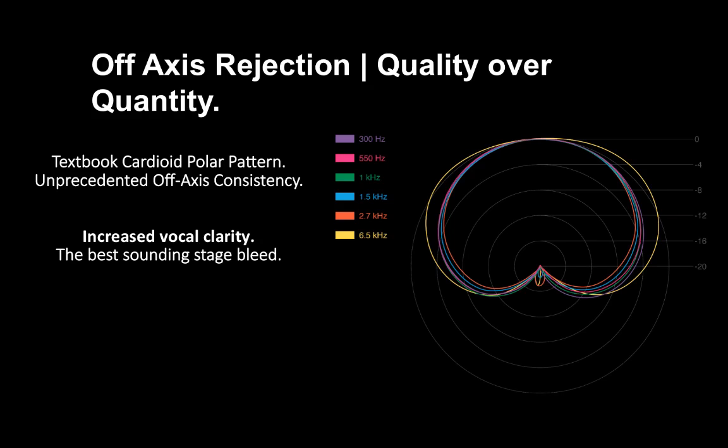And that's another thing again when you're talking about comparing microphones, right? Anybody when they just say they have a cardioid pattern microphone will show you just that basic sort of upside down heart shape. Say, look, it's cardioid, but you have to be able to look at it like you see it here at different frequencies and see, does it hold that cardioid pattern or hypercardioid or supercardioid, whatever it happens to be. At how many different frequencies does it still maintain that pattern? Because if it's really erratic at some frequencies and not at others, that's, again, what leads to that sort of colored off-axis response. But if it's consistent like this, that's the sign of a consistent pattern across frequencies, not just at one frequency.